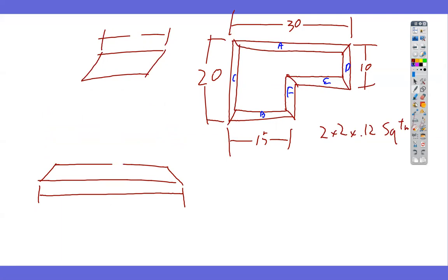So maybe up here I do a drawing for this piece, and I can call that dimension A. I tell it this is 2 inches. That's 45 degrees. There's my drawing for that part. What's the parentheses mean? It's reference, just for information. I'm using 2-inch tube. I don't want them to measure that tube and say it doesn't match the tolerance on how to block.